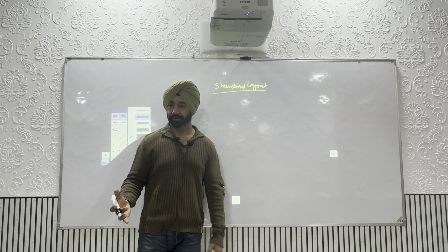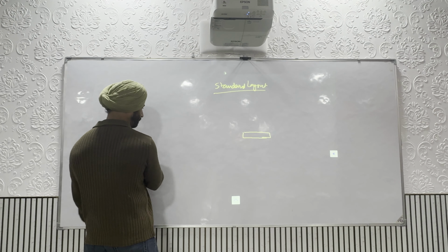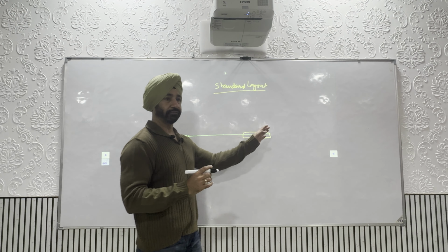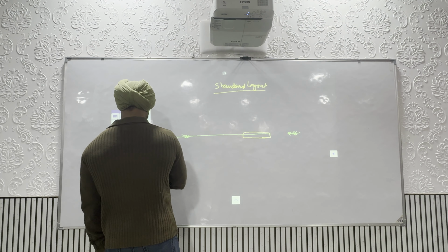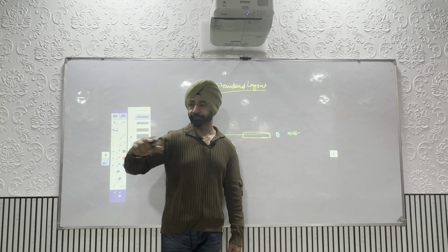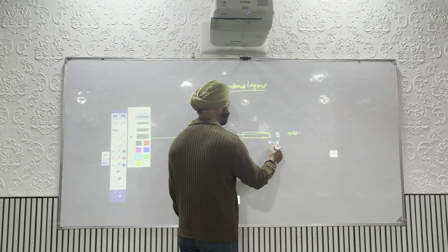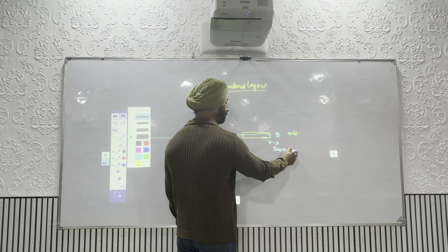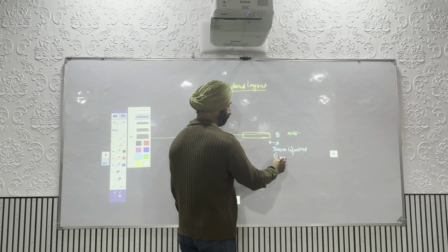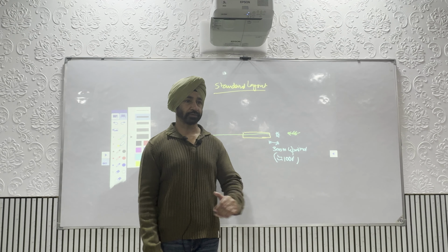Standard layout, how it should be. If this is the runway and this is your extended center line, on the other side of the runway you have a localizer antenna. In your approach direction, 300 meters upwind are those arrays of antennas which you see, the localizer. So this distance is 300 meters upwind, meaning into the wind in your approach direction, which roughly works out to 1000 feet. Glide slope antennas you have seen next to your touchdown point.